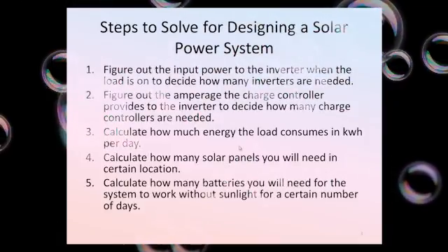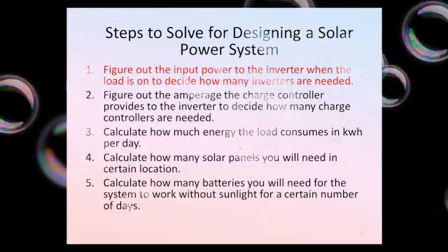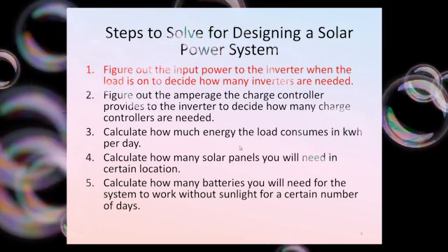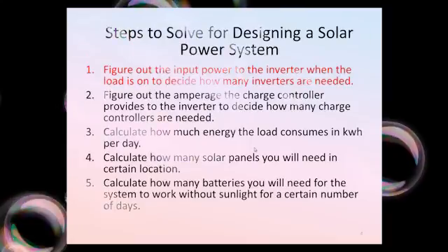Okay, so we're going to go through this step by step. The first step is we have to figure out the input power to the inverter when the load is on to decide how many inverters are needed. So let's start by finding out the input power of the inverter.